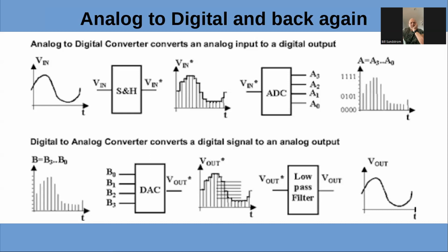No, I can't think of it. But essentially, it kind of does an envelope detection on that digital signal. It'll have a low pass filter on the output of it and give you an analog representation.